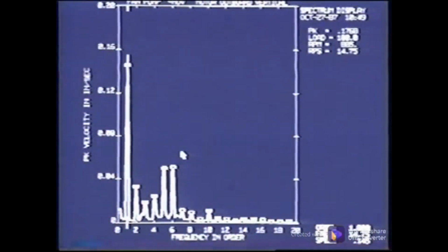This spectral data may appear to be very similar to the spectrum generated by a periodic signal because there are several multiples of turning speed present. A closer look reveals other information. These peaks have a wider base or skirt and are raised off the floor. This is not usually the case with very periodic energy.